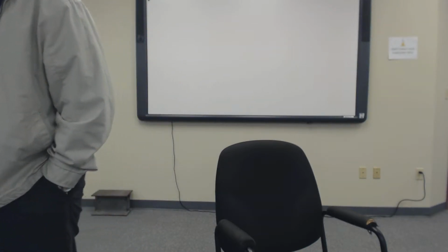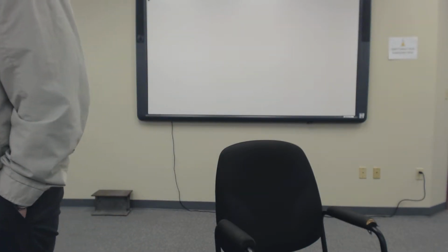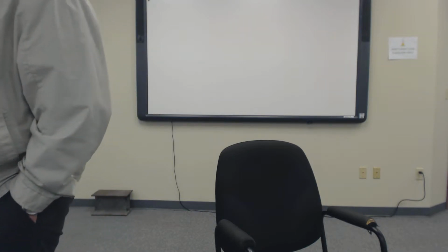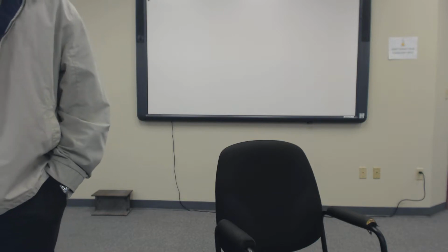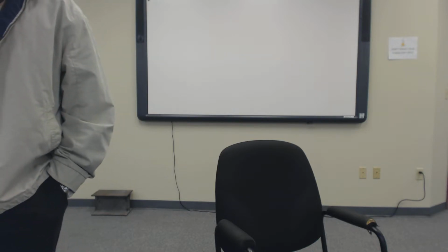With this type of system that we're doing, where you have a crawl space and then you have a wall sitting on top, or wood members sitting on top of your CMU wall all the way around, you have to put hurricane straps that go from basically the chain wall all the way up to the stud. Okay, it's called out on there, you'll see it.